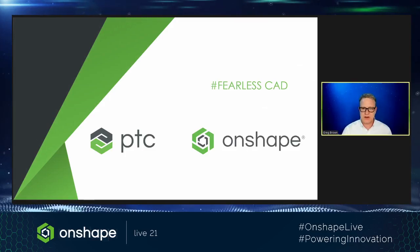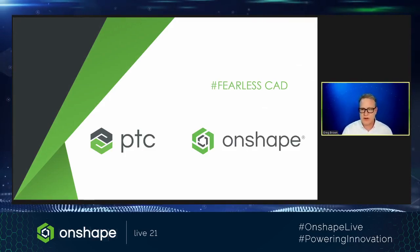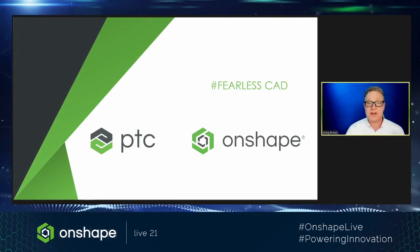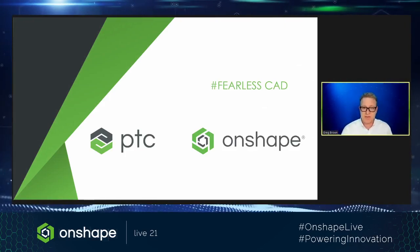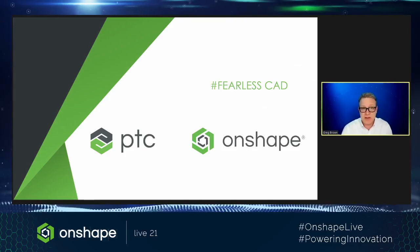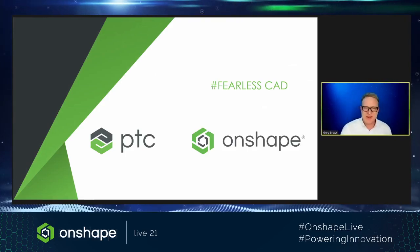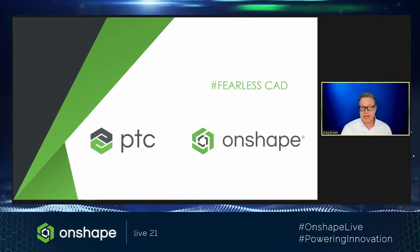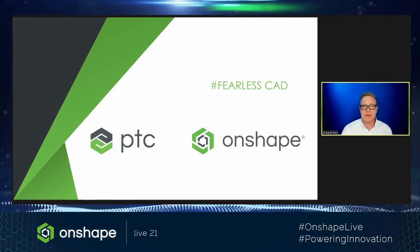Right, trying to get through this next series of questions. Is there a way to set my view normal to a face or plane in Onshape? Yes, there absolutely is. And in fact, it was like my tip number 32, something like that. It was one of my favorite tips. So you can hover over any planar face or plane and just hit the N key, right? And then that puts you normal to that plane.